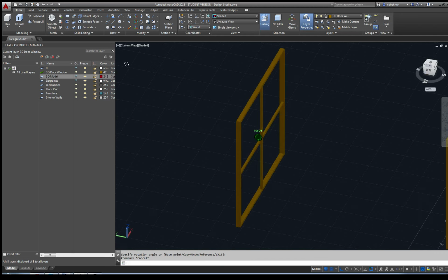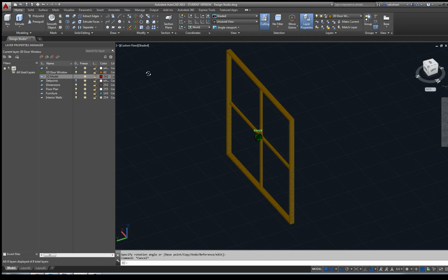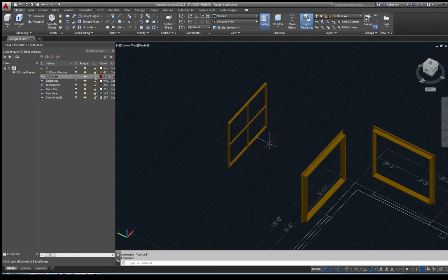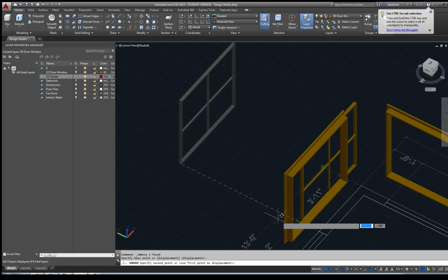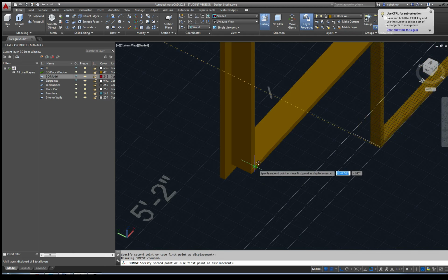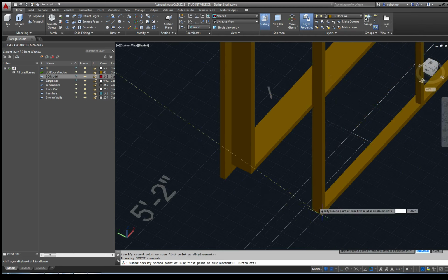So you see now my profile is outside. And now I can decide where, for example, I would like this part to fit into. So I can select my object, go to move, and say this corner point, move please to this one turned off.